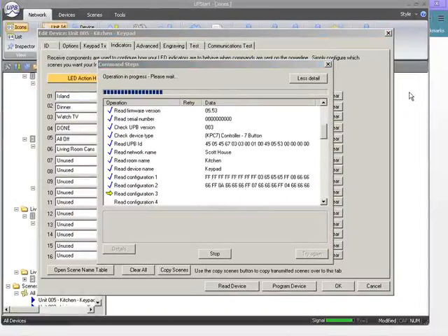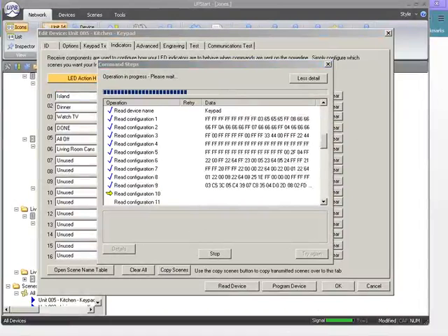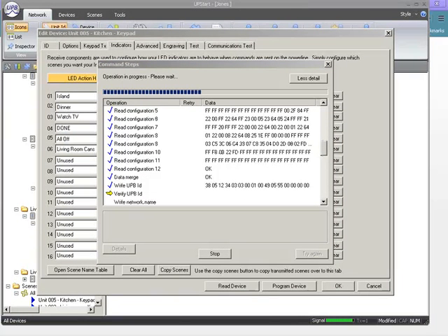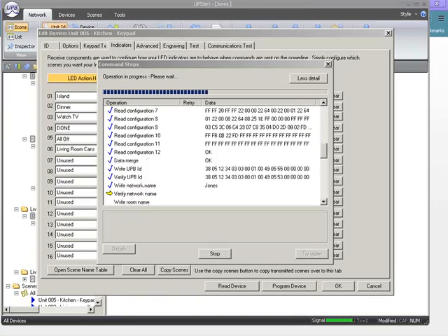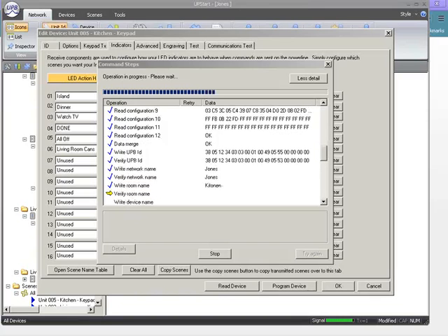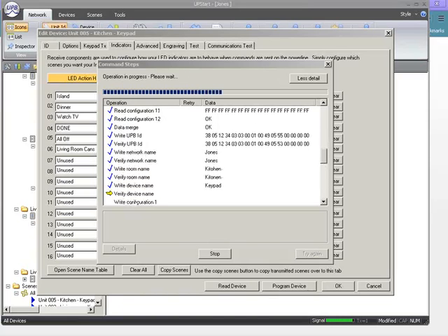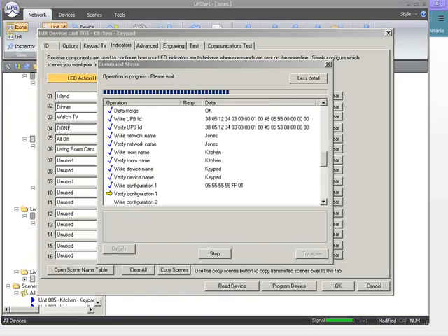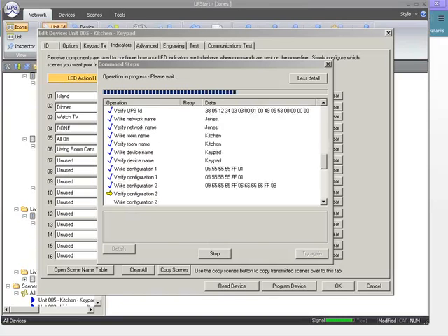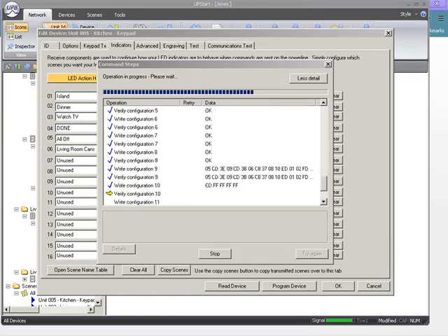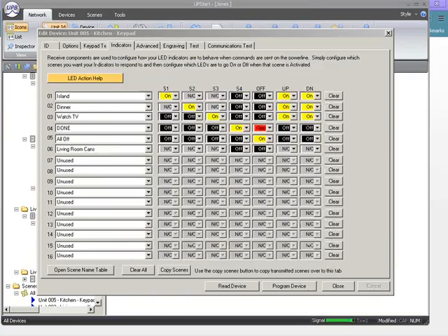Okay, the question was why it's message or pulse mode on a PIM IP, and actually on any PIM. So when I set up the configuration settings, when you're using a PIM with UPstart, it is actually talking in pulse mode. It's sending all kinds of little bitty data packets back and forth from the devices. So it's in a mode we call message or pulse mode. Whenever you're sending a scene, you're actually talking in a message. Most front-end controllers, I would say all front-end controllers, ELK, HAI, anybody that's talking UPB is talking message mode.